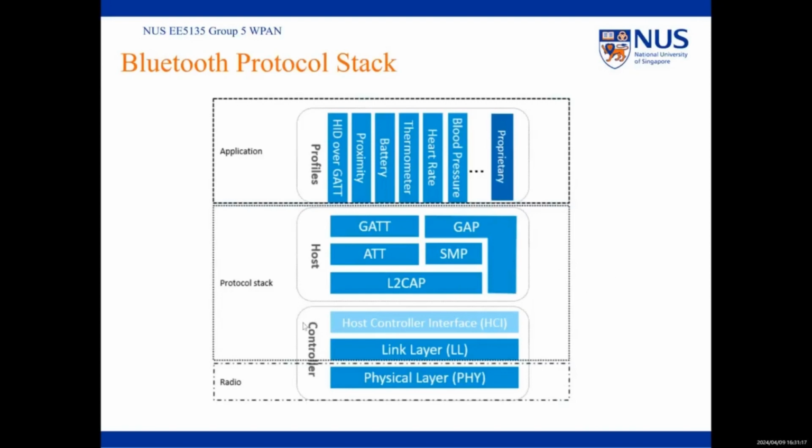First is the physical layer. The physical layer is used to specify the wireless frequency band used, and the modulation and demodulation methods. And the link layer. There are many things that the link layer has to do, such as which radio frequency channel to choose for communication, how to identify air data packets, what point in time to send the data packets, how to ensure the integrity of the data, how to receive ACK, how to retransmit, and how to manage and control the link.